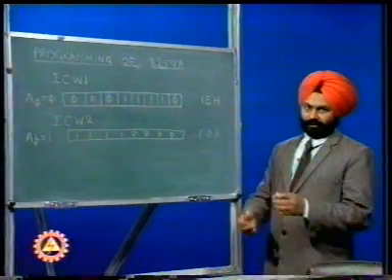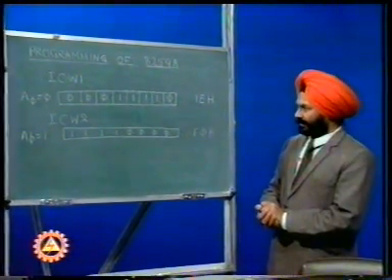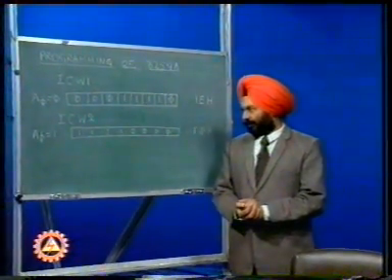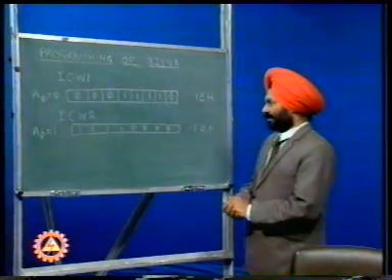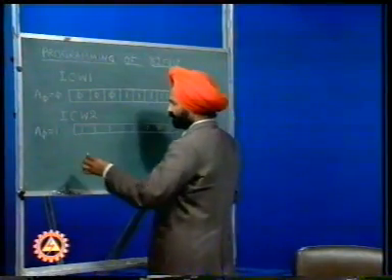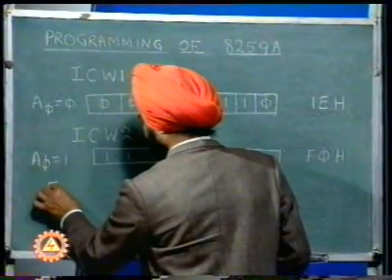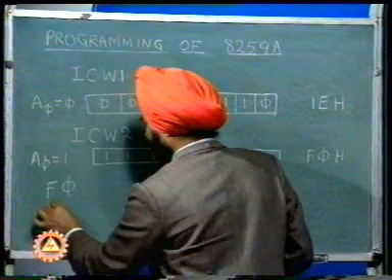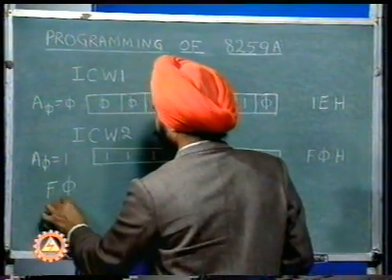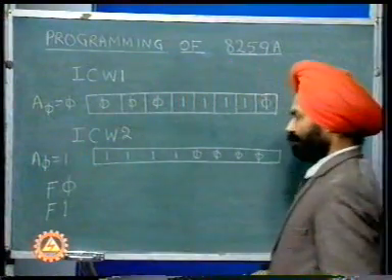Now, suppose the address decoder for the controller decodes the address to be such that the addresses of the internal registers of the controller are F0 when A0 is equal to 0 and F1 when the value of A0 is equal to 1.